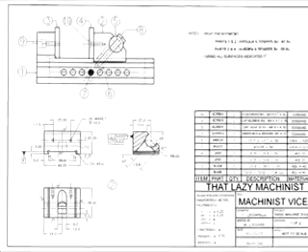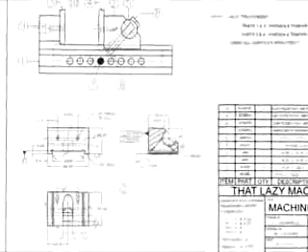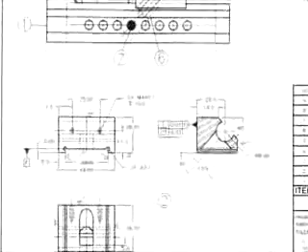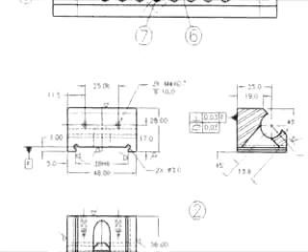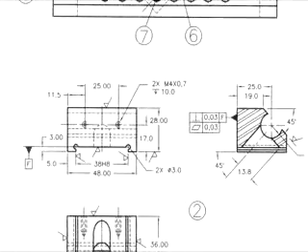It's a lot less versatile or rapid to use than a regular machine vise, but it is a lot more accurate. So this isn't a tool mechanics course, it's a blueprint reading course, and what really interests us here is the geometric tolerance. And if we read it as we see it, we can say that this surface, the surface touched by the triangle, should be perpendicular to within a tolerance zone of 0.03 of a millimeter to reference F. And this surface also has to be flat within 0.03 of a millimeter.